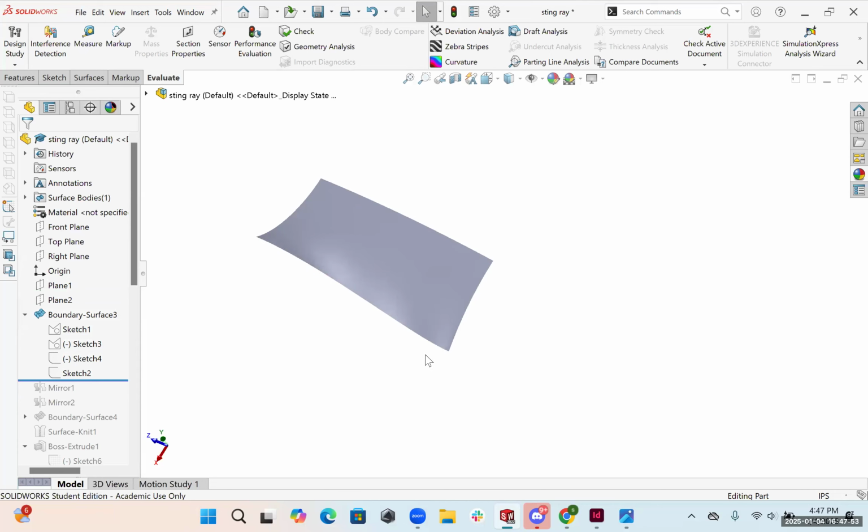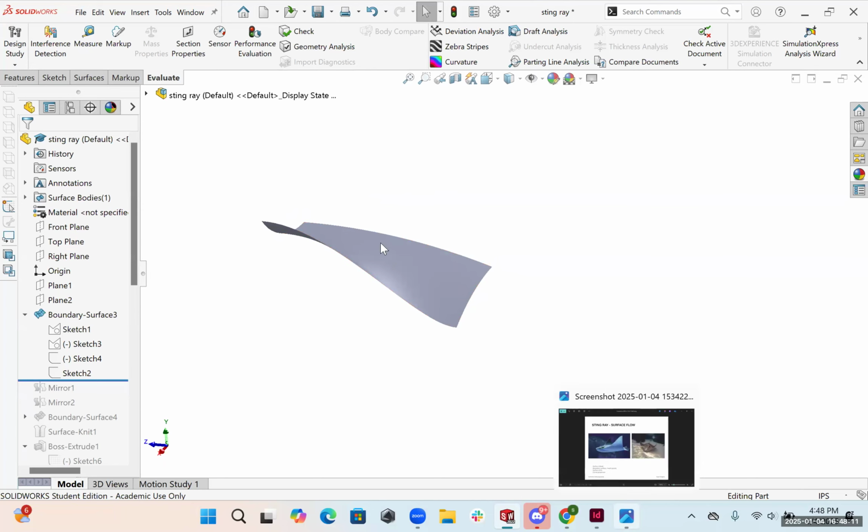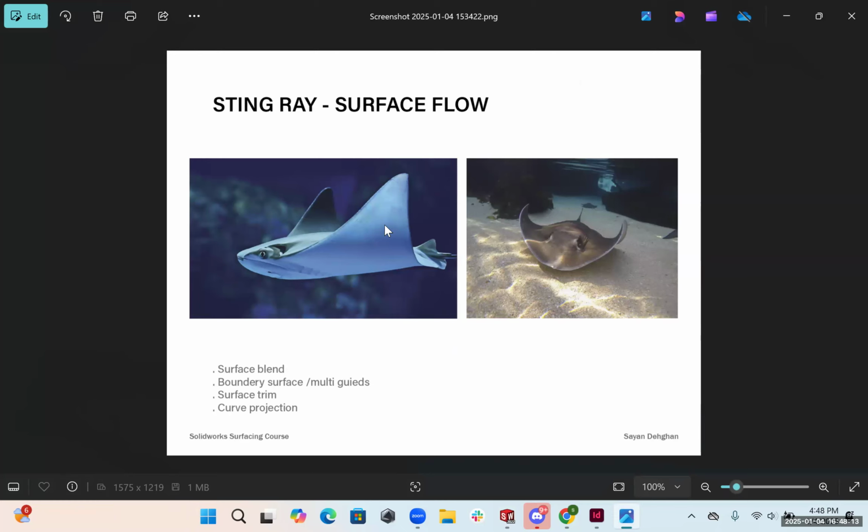So one thing that's very common in surface modeling, you do not model the surface right to the edge of the form. You go way past, so when you come and cut, you have a very clean edge. I am kind of taking an approach of making this into 4 corners because it is a symmetrical animal, and I'm kind of making it simple by saying the top wave and the bottom wave will be similar, and then when I come and cut, this portion will be cut smaller than the back.